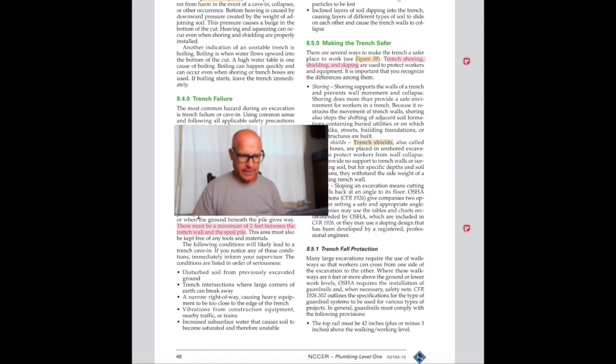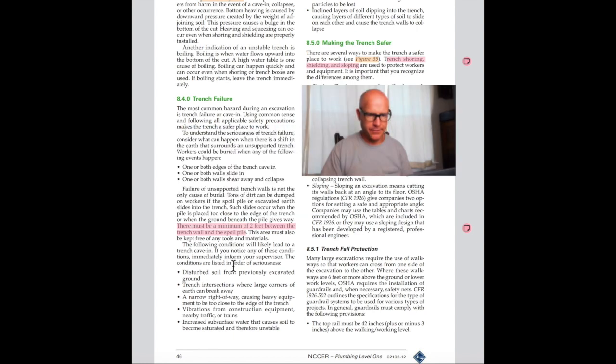A couple things we should practice. There must be a minimum of 2 feet between the trench and the soil pile. And another note, a way to make trenches safer. There are several ways to do that, but I think you should remember trench shoring, shielding, and sloping.